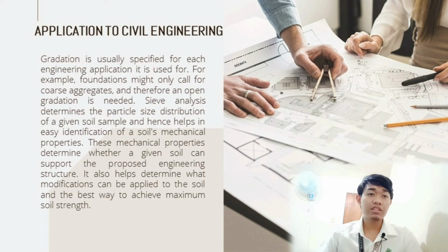Sieve analysis determines the particle size distribution of a given soil sample and hence helps in easy identification of a soil's mechanical properties. These mechanical properties determine whether a given soil can support the proposed engineering structure. It also helps determine what modifications can be applied to the soil and the best way to achieve maximum soil strength.